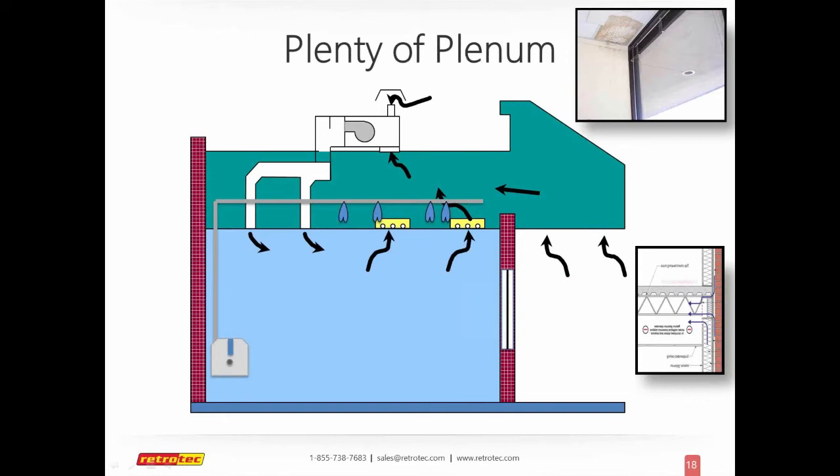One of the greatest issues that I have experienced with these types of structures, especially if they have any kind of overhang or walkways, is too much plenum that's non-ducted. What I have here in the green area would be the roof line, and this would be maybe a drop ceiling. You can see my cursor. Above here I actually have the return, which is an unducted return. They just use the open area above the ceiling as a return system, as a return path.